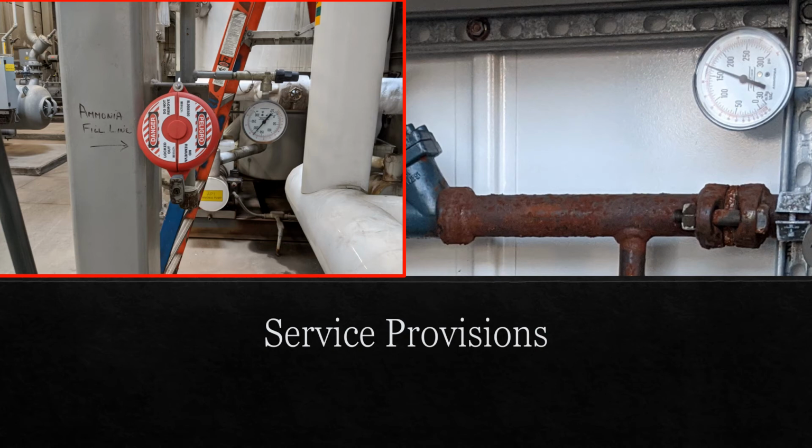This section ends by laying out the requirements for pressure gauges on the high side of the system. They must display at least 120% of the design pressure, and this section also requires that equipment have isolation valves for service and a means for pump out.